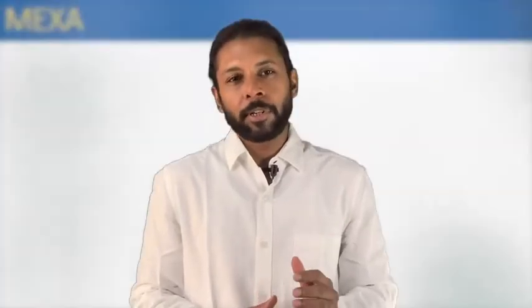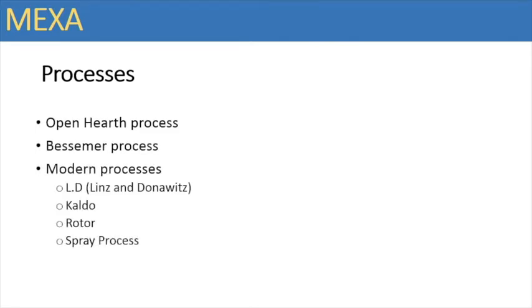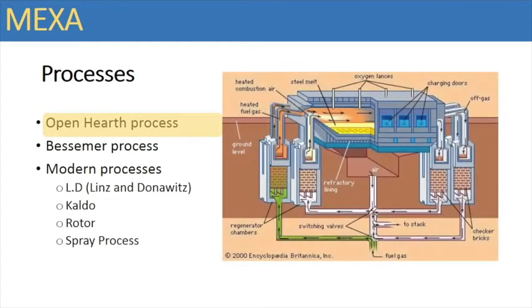To achieve the various forms of iron, pig iron has to undergo various processes. Let us briefly go through the various treatments and processes that are involved for conversion of acquired steel. Open hearth process. In this process, a broad, shallow furnace is used to support the charge of pig iron and scrap steel. Fuel employed in this process may be enriched blast furnace gas containing 30% carbon monoxide after cleaning.